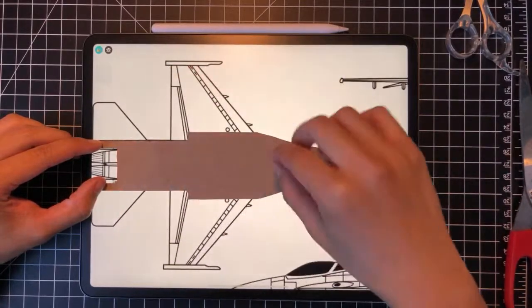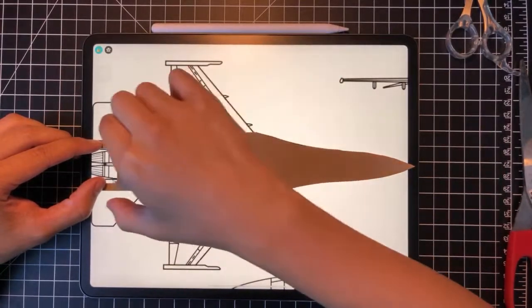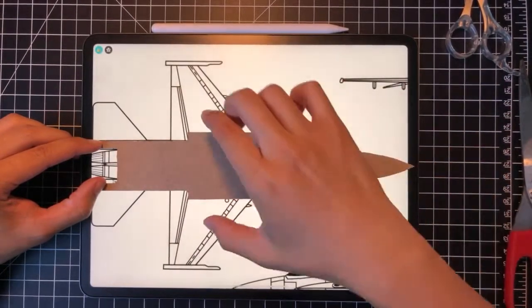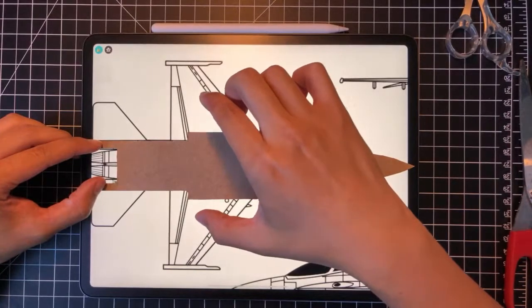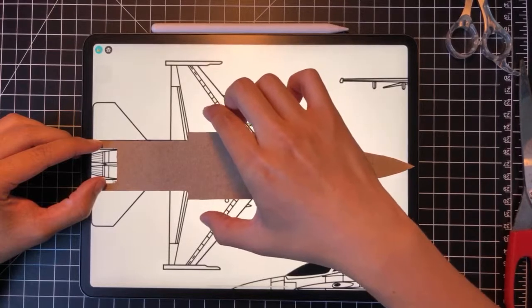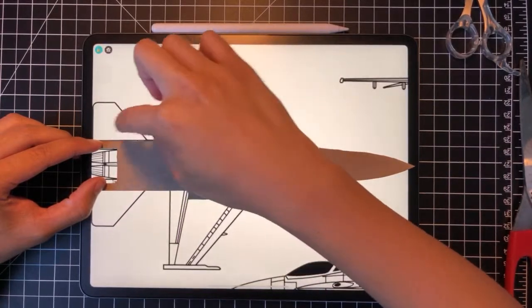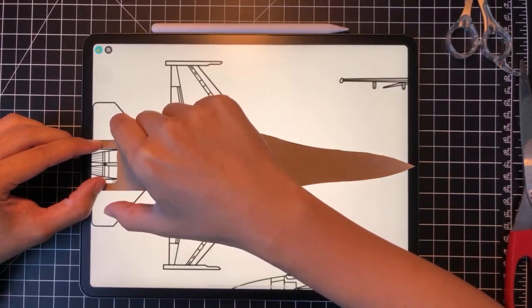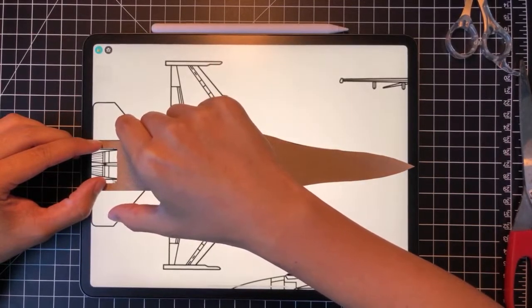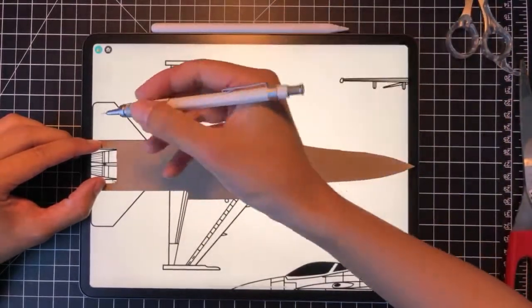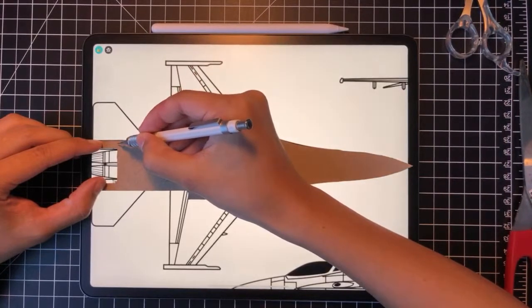Alright, so if we build our wings and our tail, because there are moving parts in the wings and the tail, I feel like we need to have those two parts ready to go. At least the wing, I should get that built and then attached. But then the tail, since it's an all moving surface, I'm not gonna build that per se, but I definitely need to know where the hinge point is, so that the actuation mechanism can account for that.